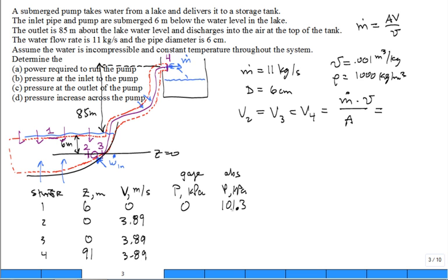All right. Well, what about the pressure at 2? Oh, I have to do a little work to get it. How about the pressure at 3? I'll have to do a little work to get it. What about the pressure at the outlet at 4? Same as 1. It's atmospheric pressure. Water's just coming out the end of the pipe. It's 0 gauge, 101.3 kilopascal. True? All right. That'll help us a little bit as we organize our thoughts.